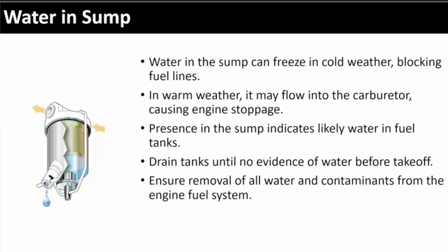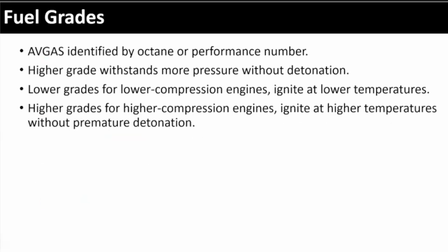Okay, so this is all the stuff we already talked about. If you get water in the lines, it can freeze, it can cause condensation, all bad stuff, whether it's ice chipping off and going into the fuel system, or water or sediment, all bad, right? So the whole idea is to make sure that you as a pilot are doing your due diligence, do your pre-flight, make sure that fuel is good before you start the engine.